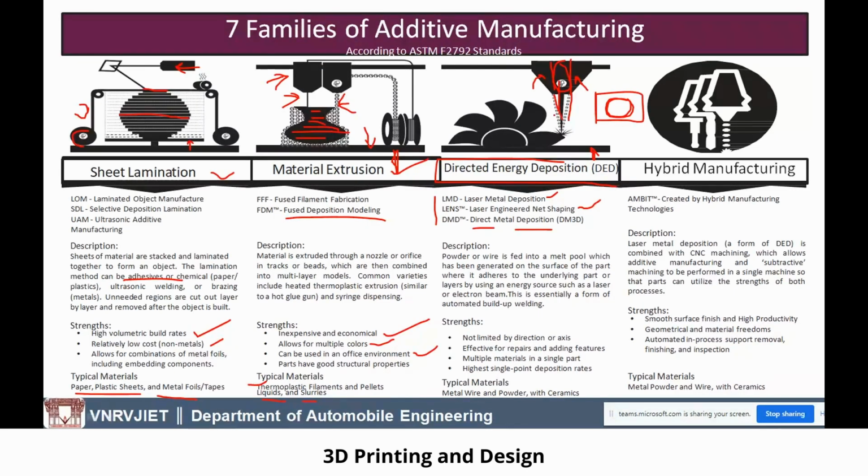And when the powder is deposited on the layer and meets the laser beam, due to the high laser heat, the powder particles will be melted, and the molten metal will be spread in a flat form in a particular direction. So immediately it will be solidified.